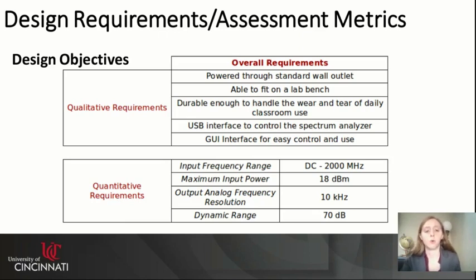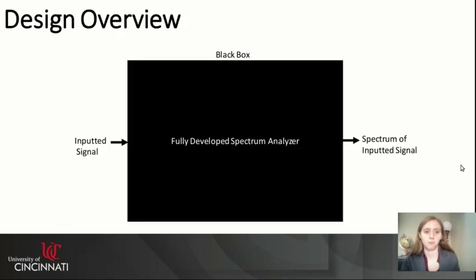Our quantitative requirements are our specifications for the actual spectrum analyzer, and they include the input frequency range, maximum input power, analog frequency resolution, and dynamic range. On this slide we have our black box design of our final product. The student can connect an input signal, such as a signal generator or an antenna, to the spectrum analyzer, and the output is a graph plot of the frequency spectrum displayed on a monitor or their computer.